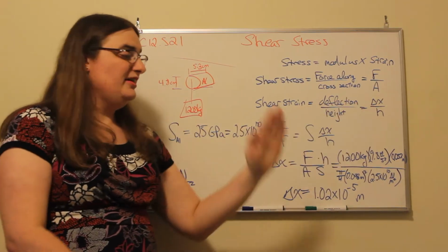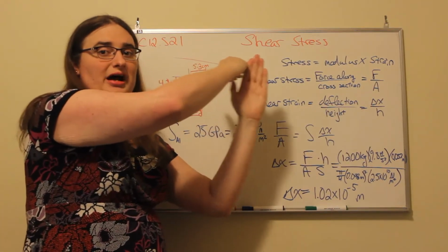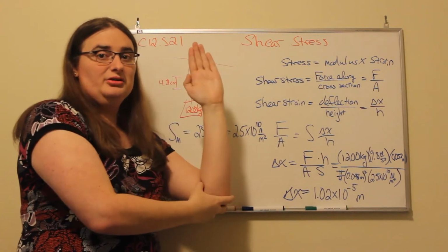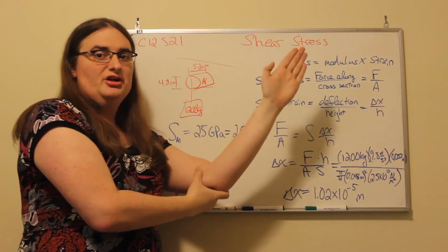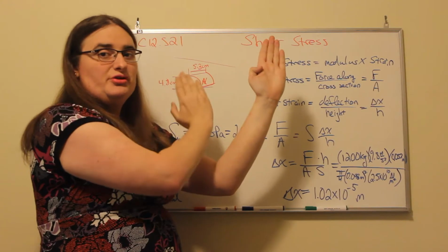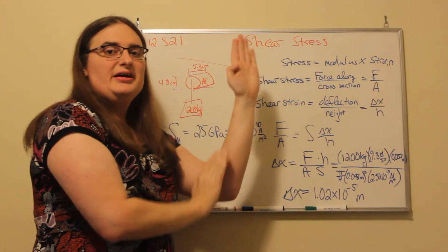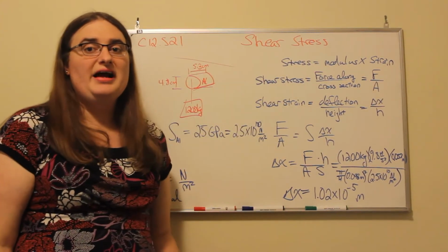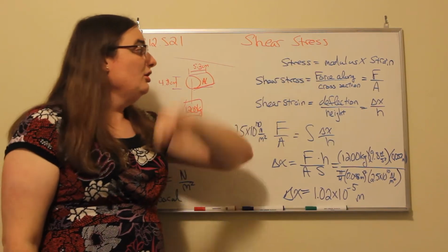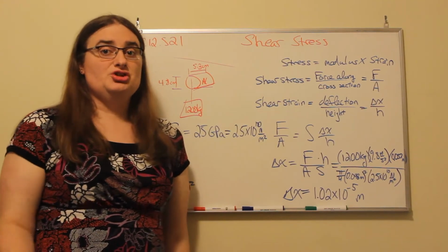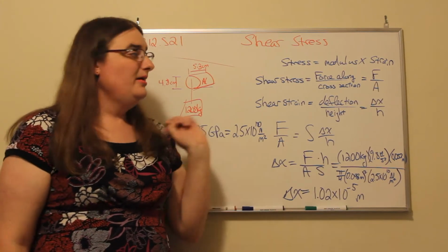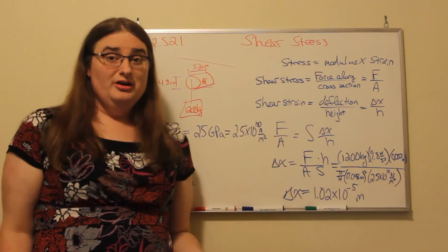The dimensionless response for a shear is how an object goes from being a rectangular parallel surface structure to more of a parallelogram type structure. What the strain is measuring is the deflection of the object compared to the height of the object. And for all stress-strain relationships, stress is directly proportional to strain, and the proportionality is known as the modulus of elasticity. And modulus is really just a fancy word for slope.